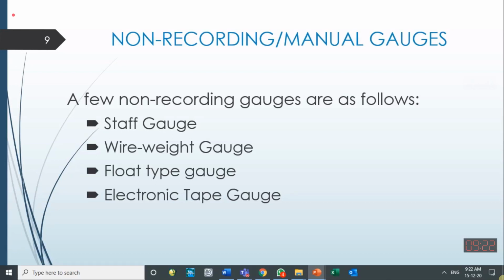If you have selected a datum for your project yourself, okay, fine. If you have selected the datum from the mean sea level, then you should find some benchmark in the close locality whose elevation is known to you. For example, a permanent benchmark by Survey of Pakistan is there close to UET, outside gate number 2, on the other side of the road.